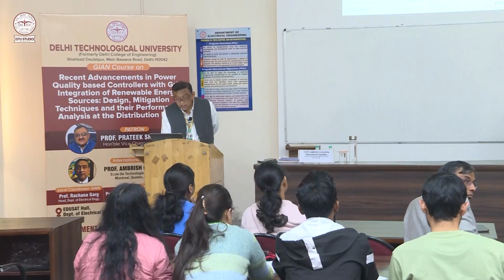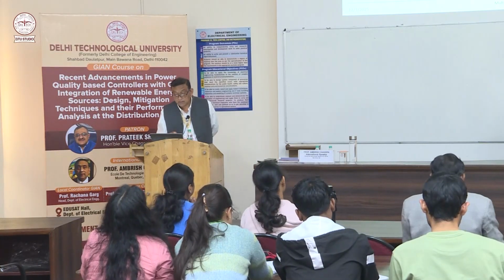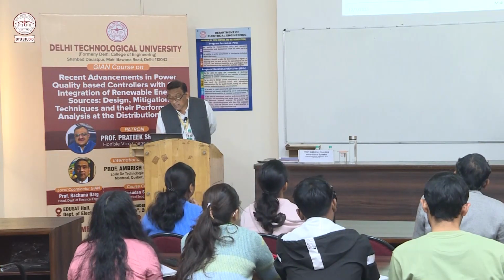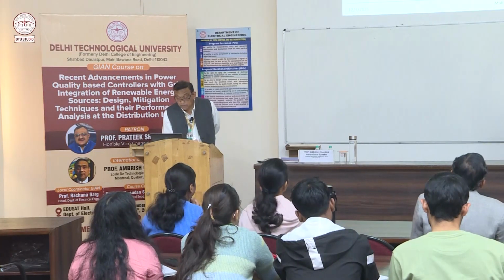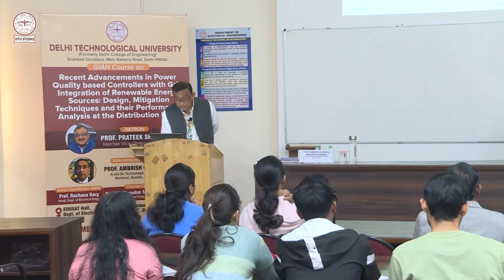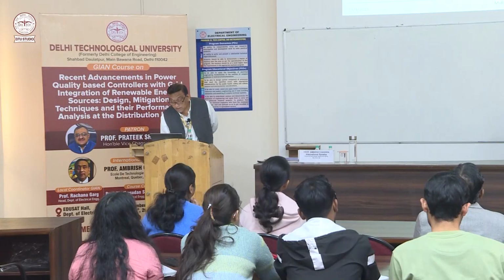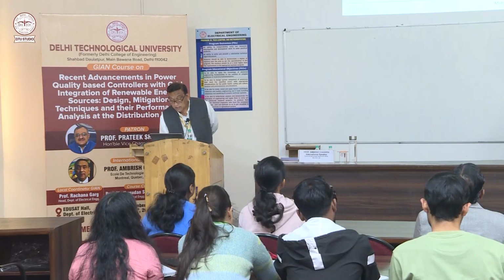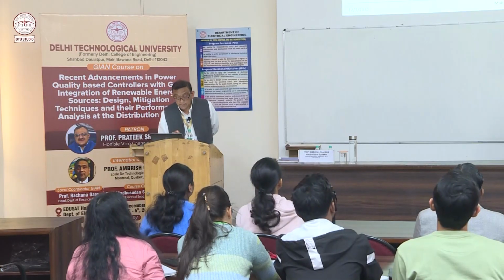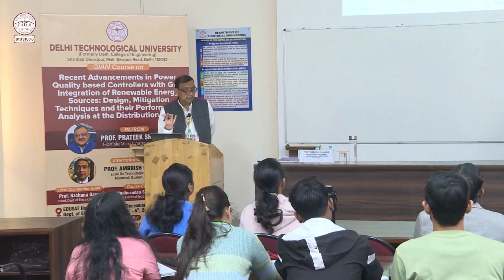If you have m converters of 6 pulse, this is the equation, and you can see this is the amplitude. If you have three converters of 6 pulse, so m is equal to 3, you have 18k plus minus 1. Three 6-pulse converters means 18 pulses, right?